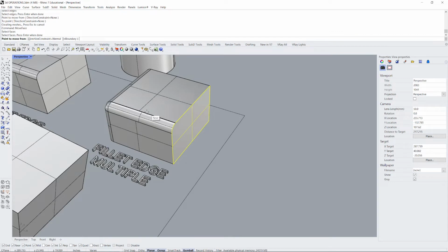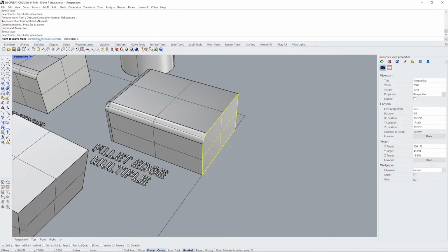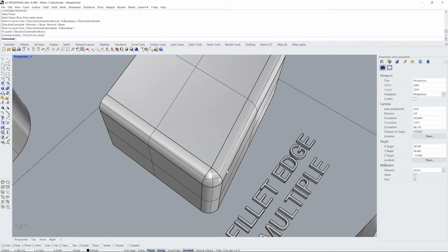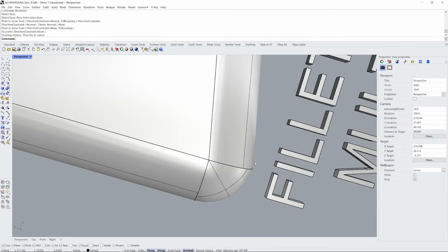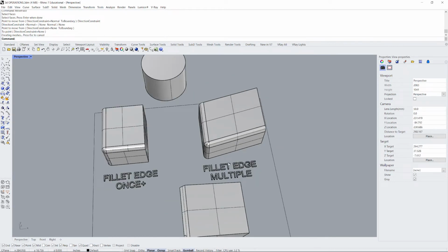It has that same tendency to break your geometry if you're not careful. So that was moving everything in the normal direction constraint. If I go with none and then I just click randomly and then I move it over here, I can mess my shape up, and things go from being a smooth radius along this edge to now a smooth radius and then a sharp transition to another radius. So you just have to pay attention to that. If it's something that you're trying to maintain, you got to be aware of it.